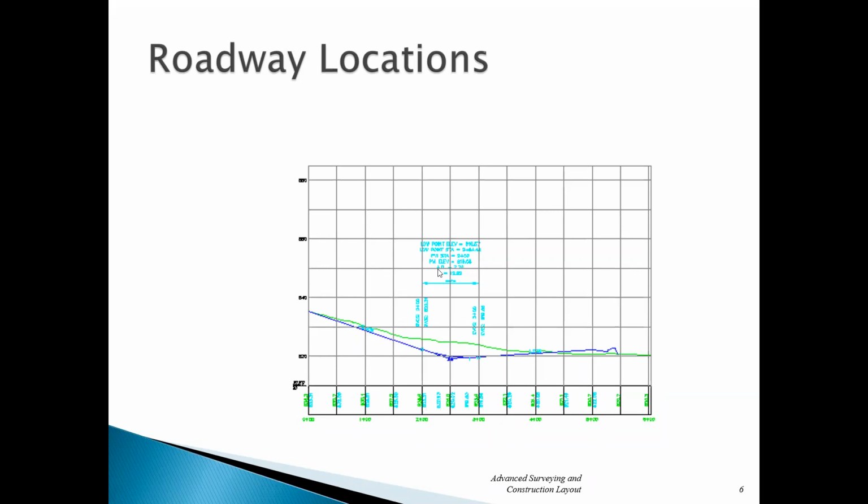And then of course you see in the cyan color blue, we see information that's relating to the profile itself. Okay, so we see like slopes, but we also see information here. This is called vertical curve. This is actually a parabola. So we'll see that parabola, we're going to go over that kind of stuff next week.